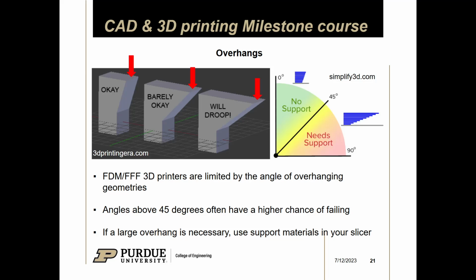Let me see. Is there a good example? Okay, so if you look at the benchy that you got earlier in class, you can see the front hull of the benchy is an overhang, right? And depending on which benchy you got, my printer may have had worse or better cooling. If you can see some pretty bad defects on the front of the hull, it's typically because it didn't have enough cooling, right?